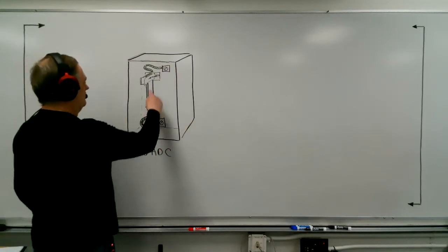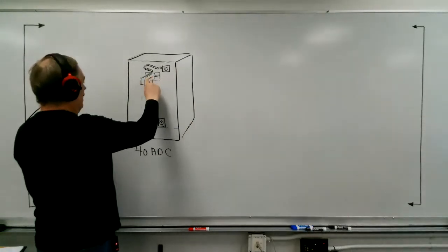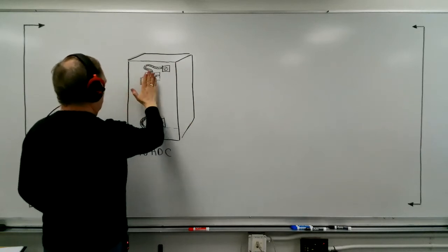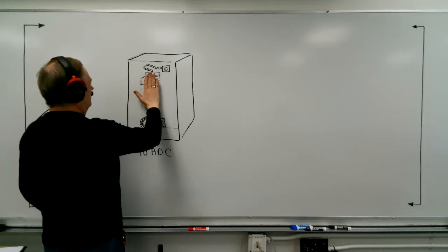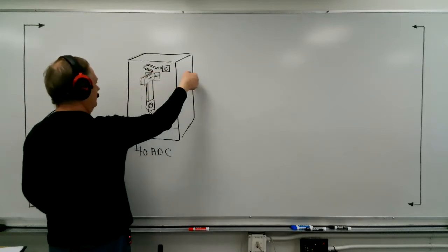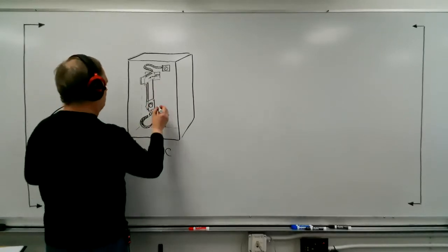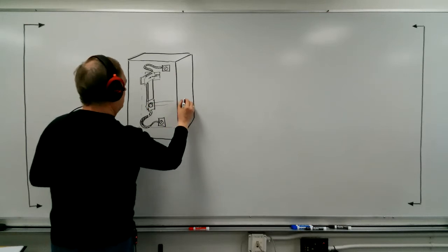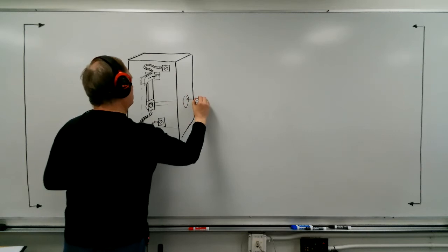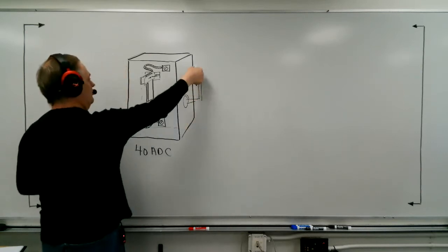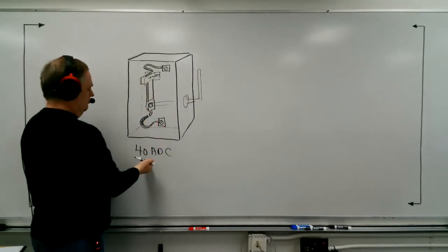Now what you would have inside would be an actual spring-loaded jaw, and then you'd have the actual arm of the switch. This blade would basically pull out. There'd be a handle on the side. When you pull this down, the handle would go through like this, essentially. It would be keyed and come through here. When you pull down on this handle, this blade pulls out, and then you interrupt your current.